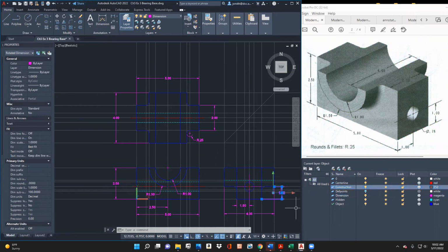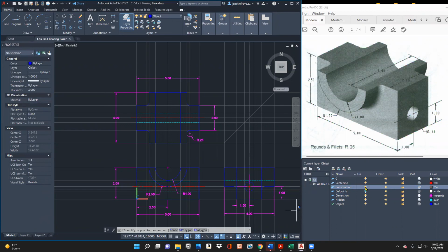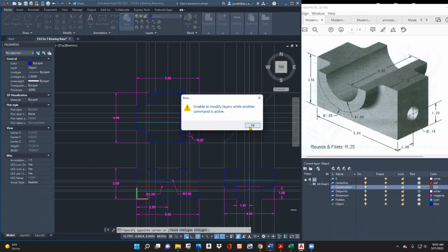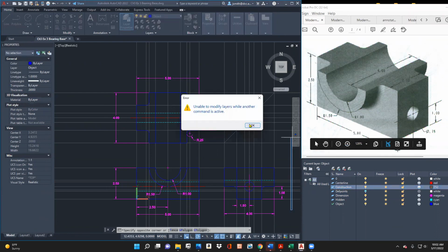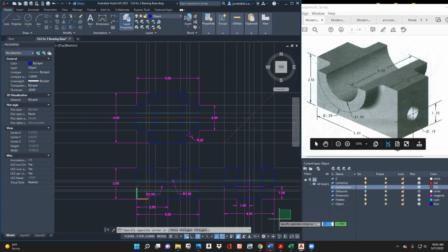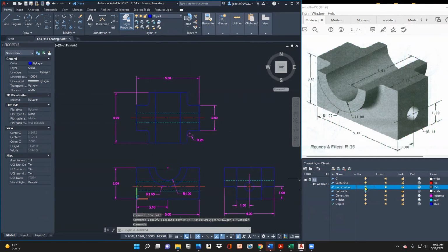So this is what it looked like. So the couple things I did here was, just to be accurate, I removed a couple of these lines here. So hang on here. Okay, so you'll see I removed, you wouldn't show that fillet from this front view, but you would want to show it on the top view and the right view.